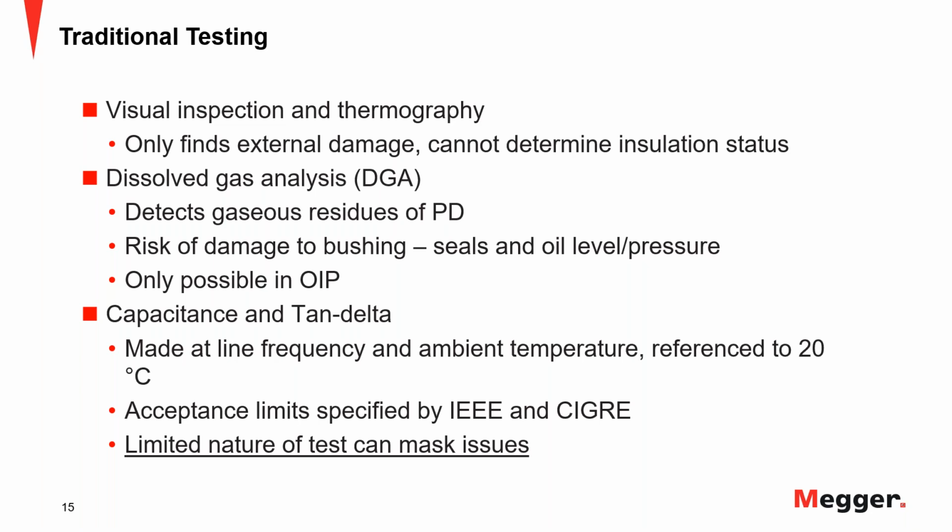Then something else that is not very much recommended, and not something that everybody likes, but it is done, especially on extra high voltage bushings, is to take a sample and do some DGA. So you look into gases, of course, with the same principle of analysis.